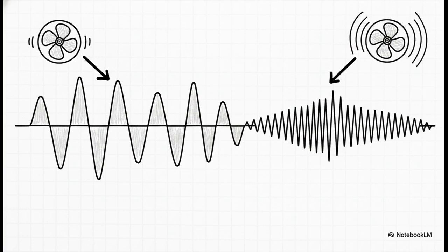Now, the absolute crucial takeaway here is all about frequency, which we measure in hertz. The rate at which those IGBTs are switching open and closed, that equals your hertz. And this is exactly what the main board is constantly varying to set the compressor speed. A lower hertz means lower synthesized AC voltage, which gives you a slower pump. A higher hertz means higher synthesized AC voltage, a much faster pump, and a whole lot more heating or cooling capacity. The inverter is literally making its own custom sine wave.